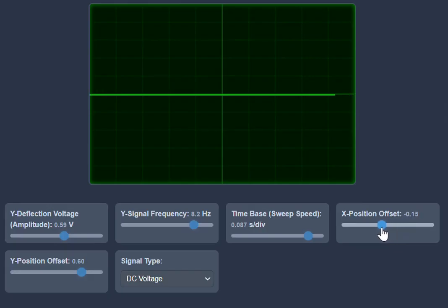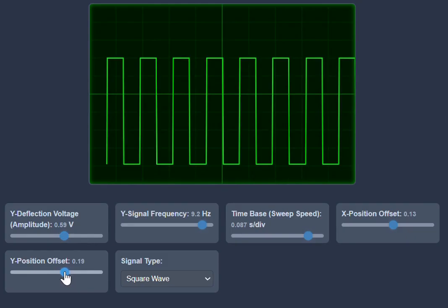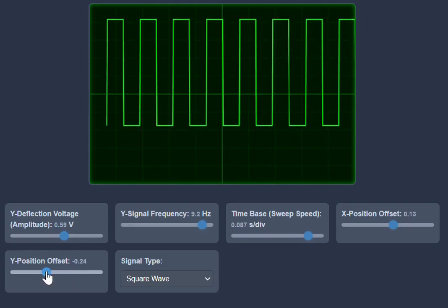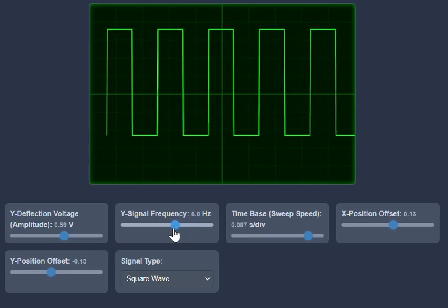Now I am generating another signal, and this is not the proper way, so it cannot be measured properly. Using the functionality key, we need to shift the signal in the up direction, so we need to decrease the offset voltage. Now there is space here, which is needed for measuring the time period.